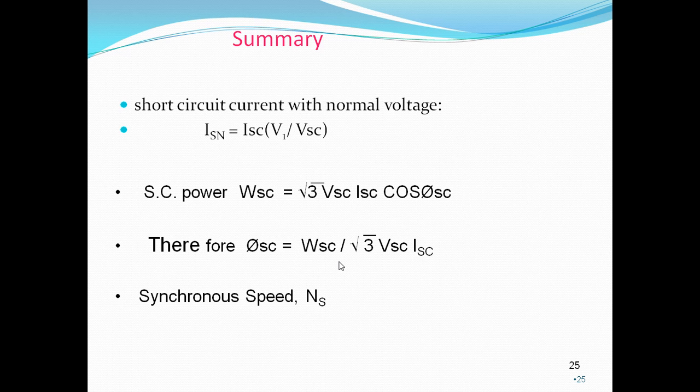If you require torque, measure FG and multiply with the power scale. If you require full load output, measure the distance PQ in centimeters and multiply with the power scale.